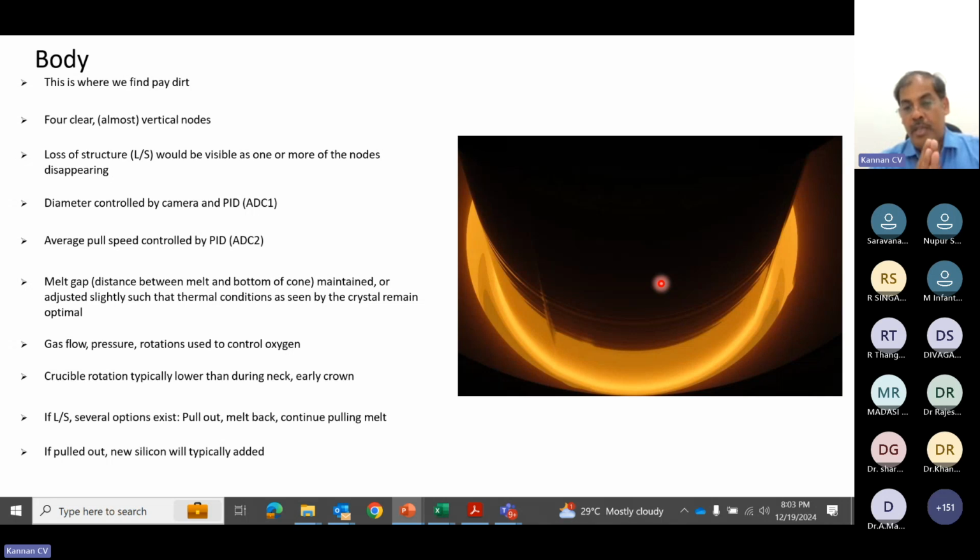So if the wafer area increases, automatically the losses also will increase. The carriers generated have to travel a long distance. So obviously we need a smaller, optimized size where you can get more power and at the same time less losses. So the maximum diameter the PV industry is using so far is 300, whereas the semiconductor industry has already achieved 400 diameter crystal.